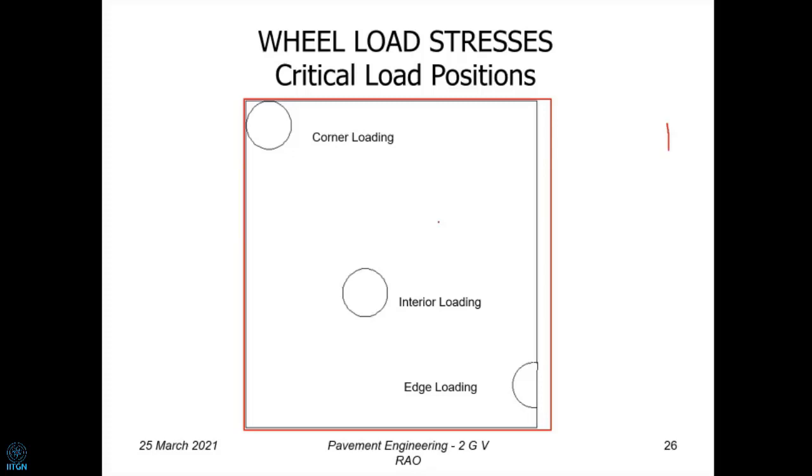And the friction stress is going to come because of the uniform movement of the entire slab. And because it is resting on the ground, naturally stress is there. But imagine that it's not on the ground, just for a minute. If it is a free body, there's no stress on that. Maybe if you have a contact and expand, there's no stress on this. But the stress is coming because it's resting on the ground. So that way it becomes a very complicated kind of system. And naturally friction can vary because of moisture content, because of freezing and all.